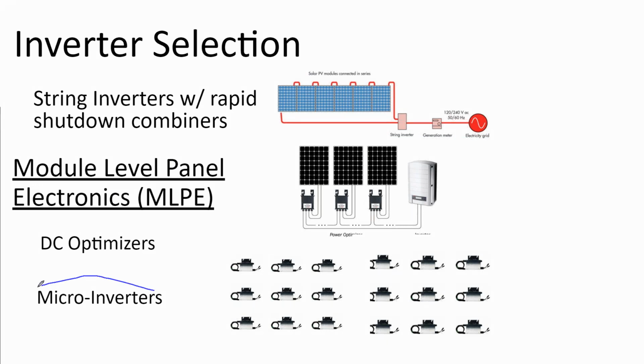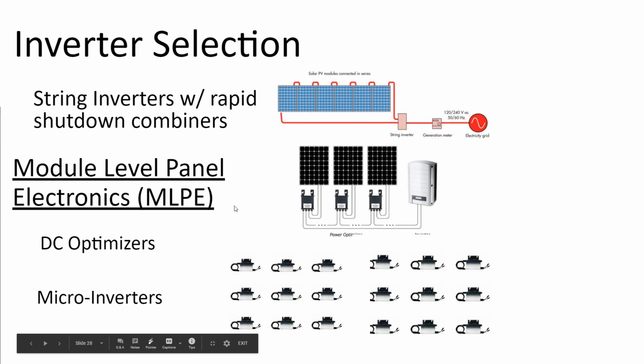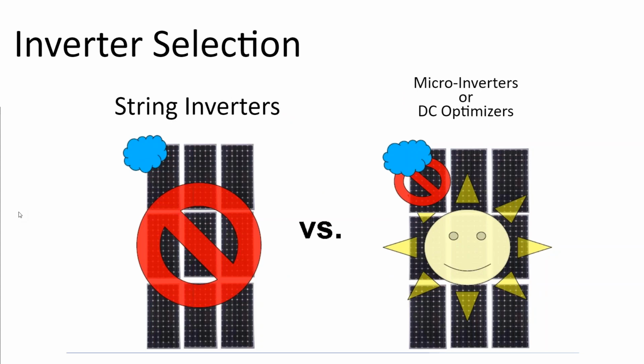The reason that microinverters and DC optimizers were invented is different than the reason that we use them today. It used to be that sunlight was good for solar and shade was like the Black Plague. Shade was the COVID-19 of solar design. You get a little bit of shade on your whole array, and it starts having impacts throughout the entire system. So what would happen is a little bit of shade would shade one panel, and it would either turn off the panel entirely, or it would cause the panel to drop by one third or two thirds, and that would also put a kink in that entire circuit, and so the entire circuit would drop down to one third or two thirds or nothing at all until the shadow would move.